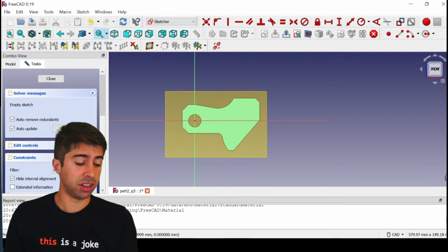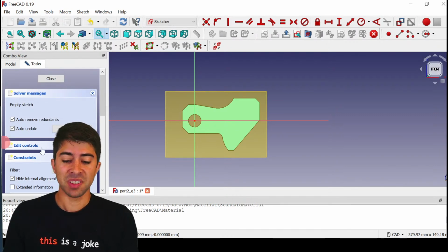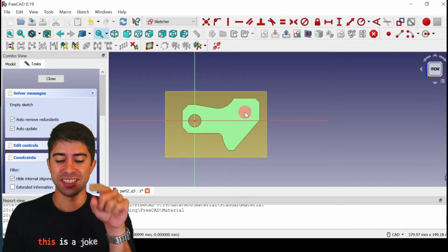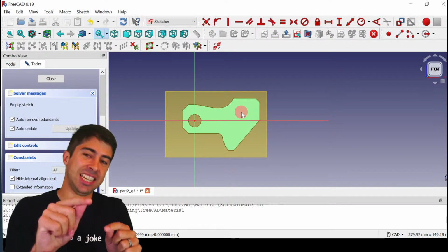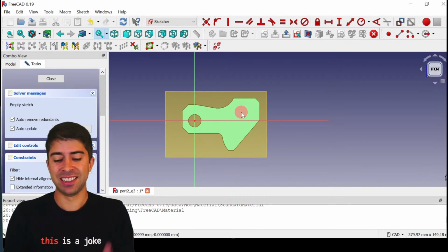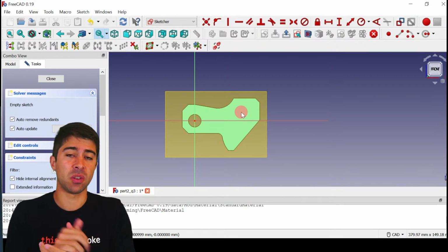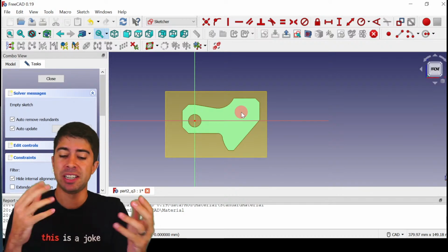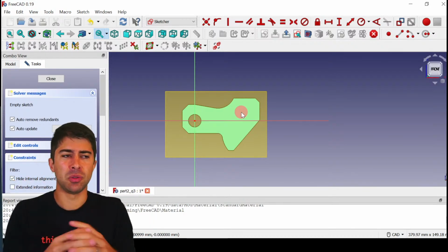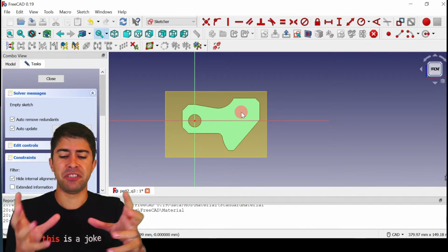Yes, so Ratul, like you said, I tried selecting the front face of the part and then nothing happens, because obviously in SolidWorks it pops up, say, oh, new sketch, and you say, yes, please, and you just get going. Versus here, it's a bit more involved. And I know there's issues, they call it the FreeCAD topology issue, where if you update it, it's got some naming issues where it renames certain features of your part.